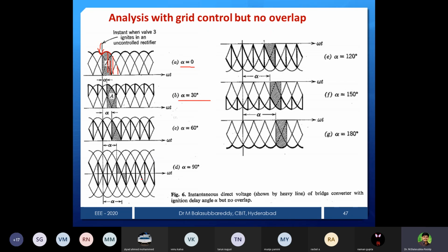As per power electronics logic, for a 3-phase full converter, alpha equal to 0 gives all 6 pulses like this, and alpha equal to 30 degrees will be like this, all 6, and alpha equal to 60 degrees, it reaches natural 0. Beyond that, if I fire at a larger alpha, with an RL load you will get negative conduction also. At 90 degrees, the output is 3 root 3 Vm by pi into cos alpha. With that logic, cos 90 is 0, so the output voltage is 0, therefore the positive and negative magnitudes are equal. That is the reason we get this 90 degrees case, with positive as well as negative magnitude, and so on.